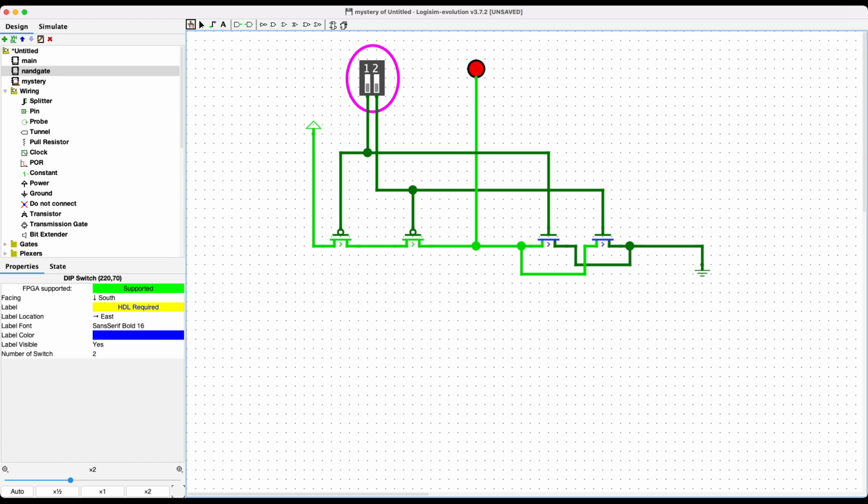Well, there's 5 out of the 7 basic ones. We've got AND, OR, NAND, NOR, and NOT, and then what are the only 2 that are left? XOR and NXOR, and we can build those with combinations of these things. Okay, all right, so does that kind of make sense, this complementary structure? Yeah, okay. And the brilliance is by having the complementary structure, because there's good electrical reasons for that, in terms of where current's flowing and heat dissipation and things like that.